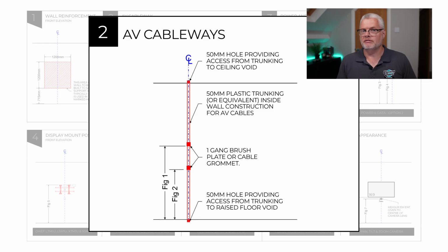To route these to the various components, cable routes need to be established. And during the first fix, this is the part where they're putting the frame up, we need to tell the construction teams what is required and where. And this must be done before both sides of the plasterboard have been put in place, because we need to be able to run those cables.